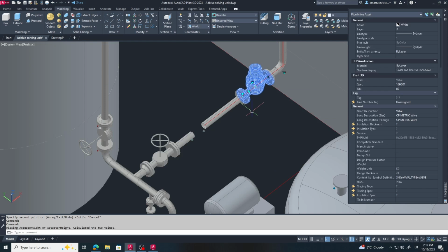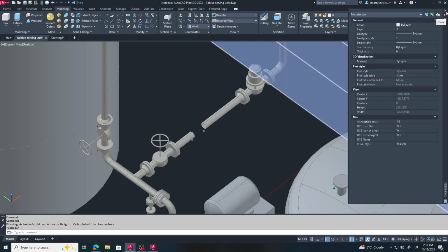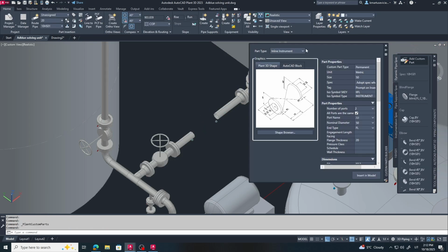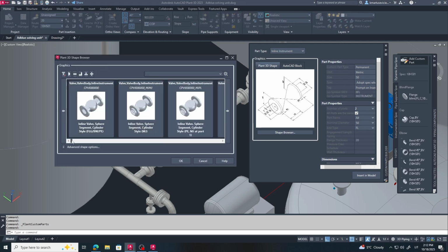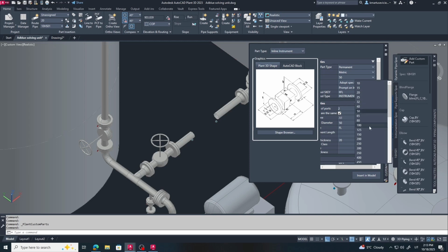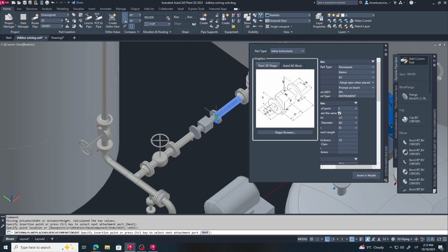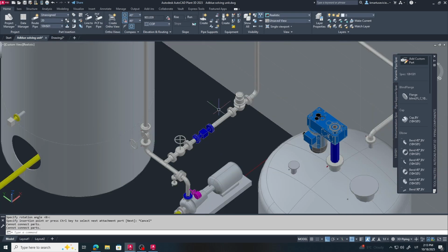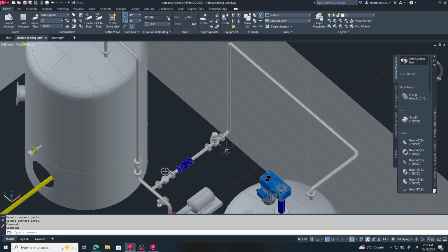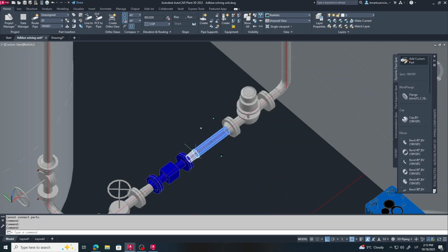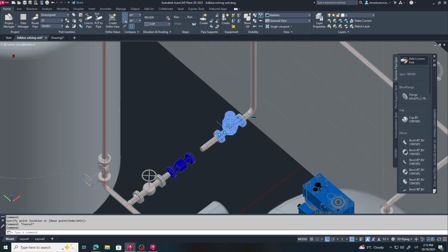And eventually we select the proper flowmeter for this application, making sure it matches the line size, flow range, and accuracy we need. Flowmeters always need straight pipe distances before and after the device. This stabilizes the flow profile and ensures accurate measurement. Usually we keep a few pipe diameters of straight run upstream and a shorter section downstream, depending on the flowmeter type.